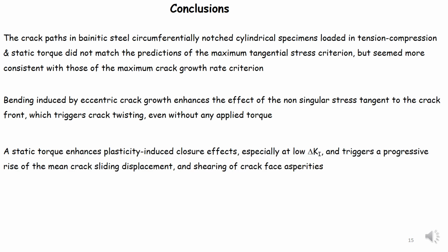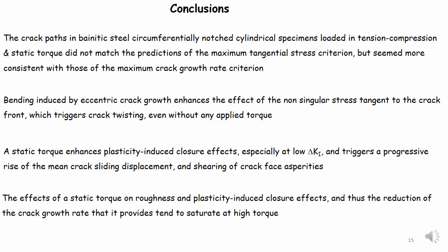A static torque enhances plasticity-induced closure effects, especially at low delta K, and triggers a progressive rise of the mean crack sliding displacement and shearing of crack face asperities. And the effects of a static torque on roughness and plasticity-induced closure effects, and thus the reduction of the crack growth rate that it provides, tends to saturate at high torque.